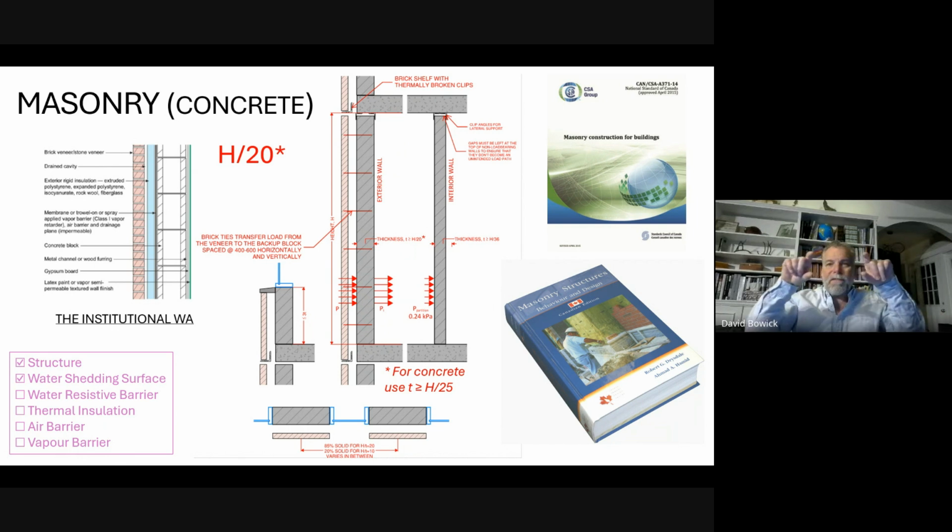That's true even if it's a skinny little strip window. You can have a window that looks 99% solid, but you've cut a little strip window in it. You cut the section through that window, and at that section, you have 1 meter solid, 5 meter window, 1 meter solid. It's 20% solid for the purpose of application of this, because you've cut that little strip. Okay. So H/20, 190 millimeters, 85% solid, or else you change your H/20 rule.